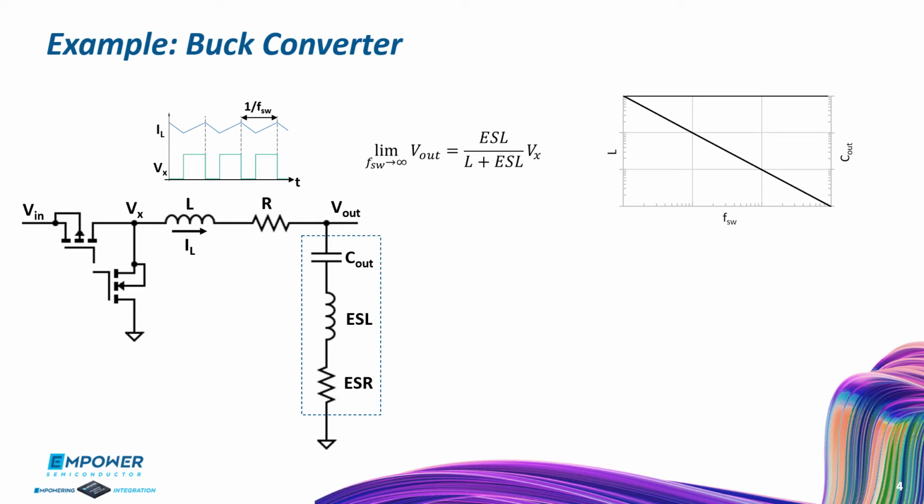Now, if we are designing for high-density form factors and are dealing with space-constrained systems, we need to increase the switching frequency to reduce the size of the filter components to acceptable levels. As a result, we are increasing the high-frequency gain of this filter, making it less effective at those high frequencies.